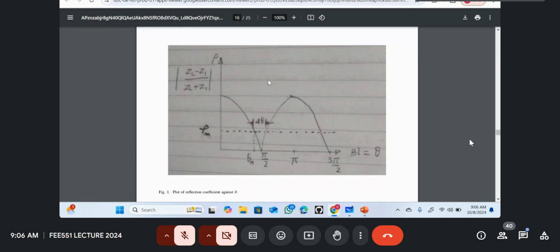They gave us an example with 3 sections. You could have 2 sections, as I gave in the examples. It's just to increase that bandwidth so that within it, for the frequencies applied, the reflection coefficient will be below that threshold, rho m, because you need to operate where the reflections are limited. In this case, you can see that the curve repeats itself for every pi.